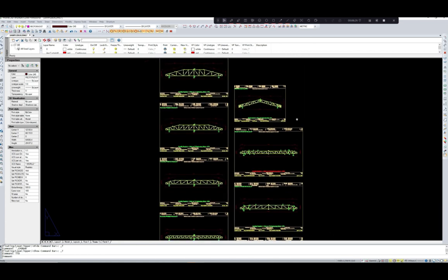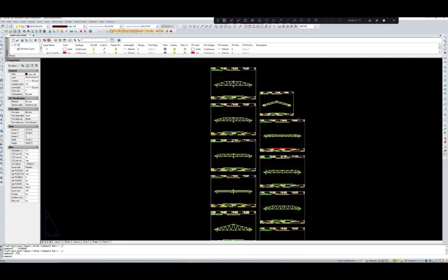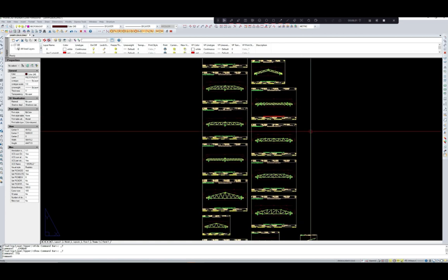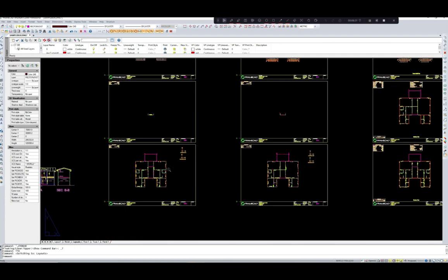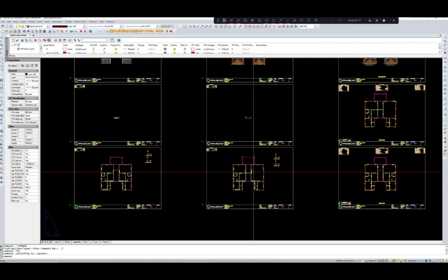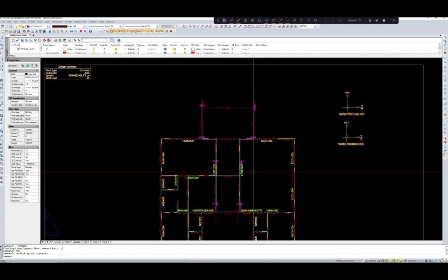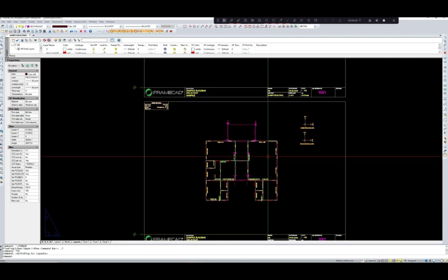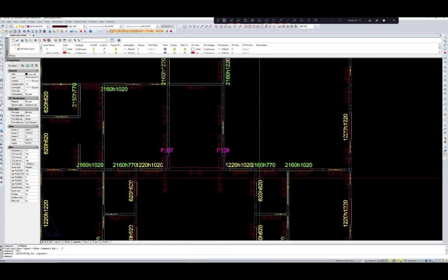The next part of this is preparation of erection drawing. While preparing the erection drawings, the layout drawing will be sufficient. We have to provide the dimensions, but looking at the reactions, we have to provide some hold downs at locations wherever the bracing reactions are quite high.